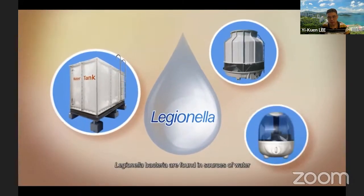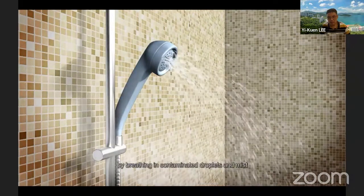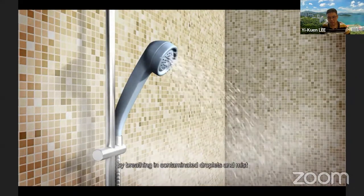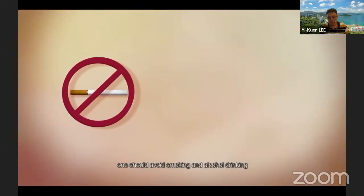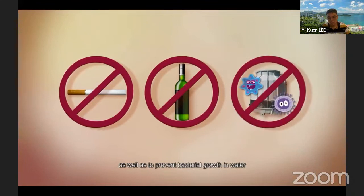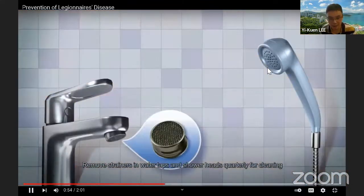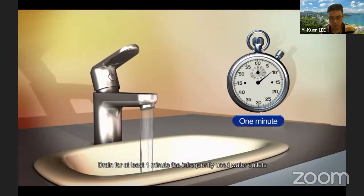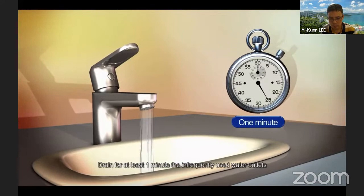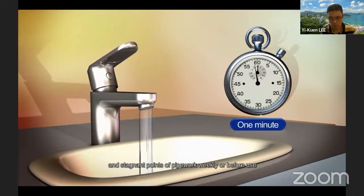Legionella bacteria are found in sources of water. A person can develop Legionnaires' disease by breathing in contaminated droplets and mist. To prevent the infection, one should avoid smoking and alcohol drinking, as well as prevent bacterial growth in water. In this kind of cooling tower. Remove strainers in water taps and shower heads quarterly for cleaning. Drain for at least 1 minute the infrequently used water outlets and stagnant points of pipework weekly or before use.